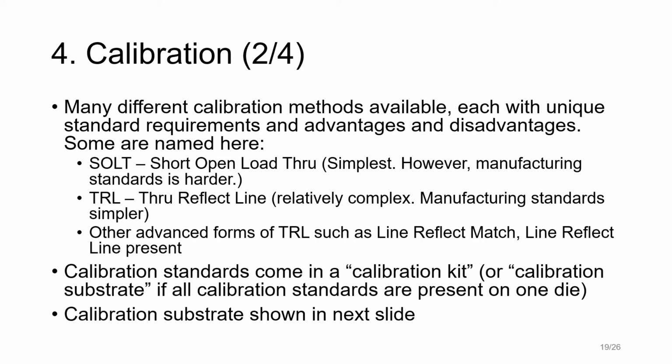We had noted in one of the introductory slides how the response measured by the VNA is not purely the response of the device, but also the response of the cables, connectors, and all other accessories that are on the path to and from the DUT. We had noted the need to remove the effect of such elements in order to correctly obtain the response of the DUT alone. This happens in the calibration stage. It is important to remember that calibration is done with the help of standard structures whose characteristics are known beforehand.